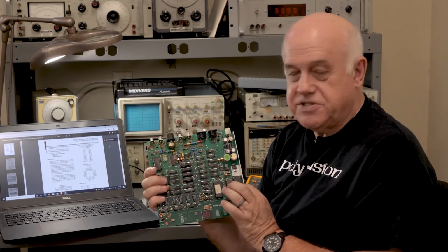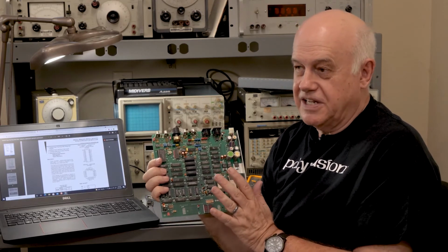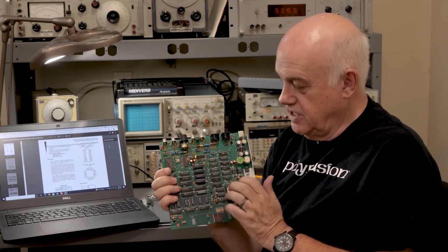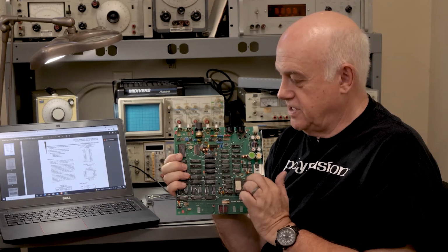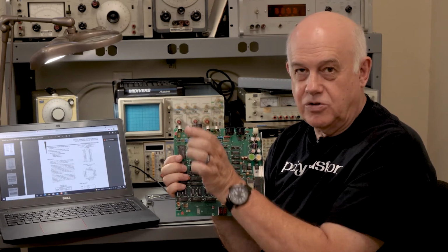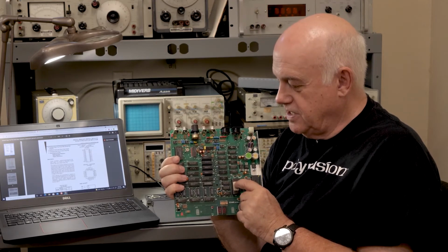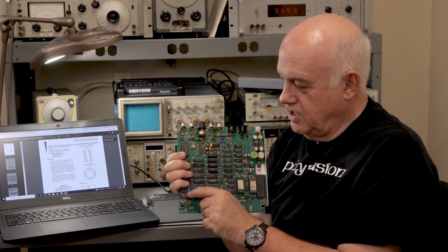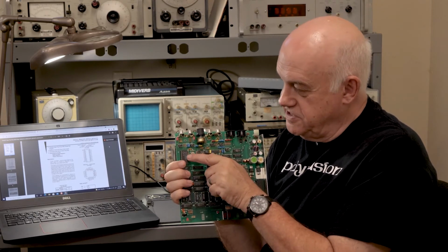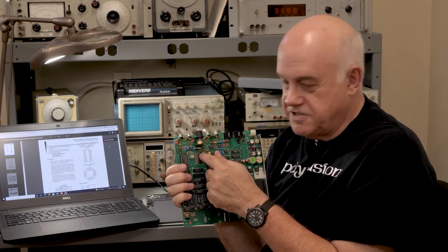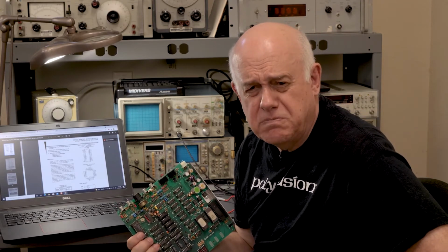What was interesting about this design is that, and I can't stress this enough, because I've only seen this once before, on purpose, Barr did not hook up the data bus the way I call normal parallel. Bit 0 coming out of the EEPROM is always D0 on the part, which goes to D0 of the memory, which goes to D0 of the SAR, which goes to D0 of the DAC, because that's the way you're supposed to do it.